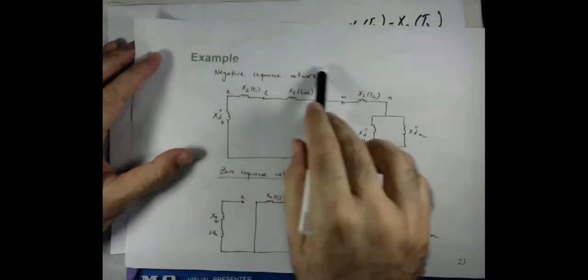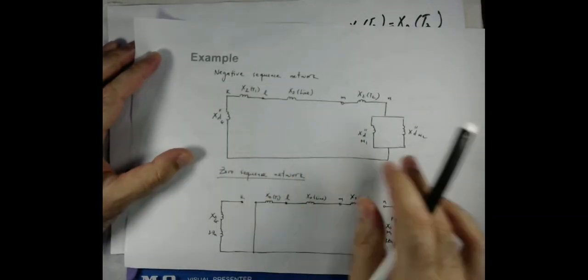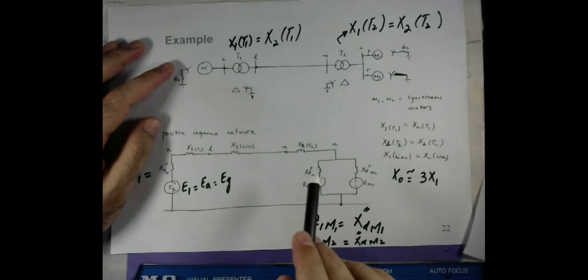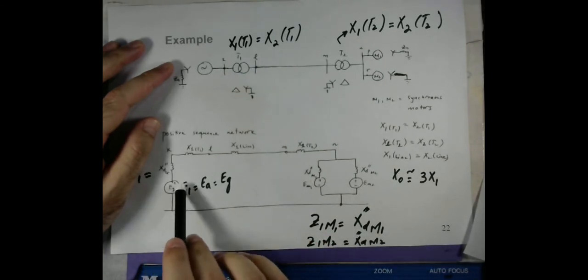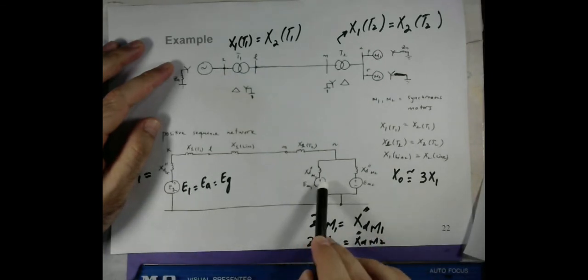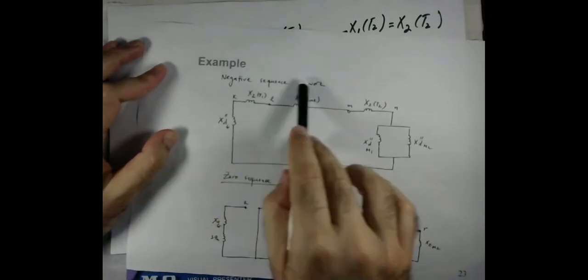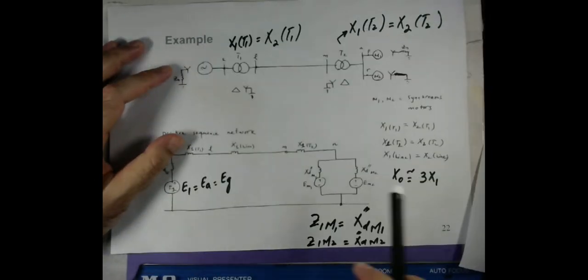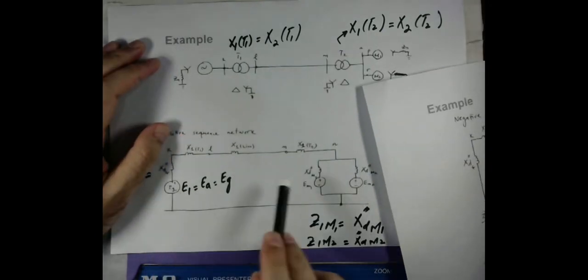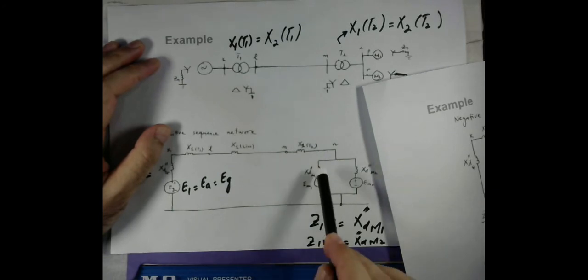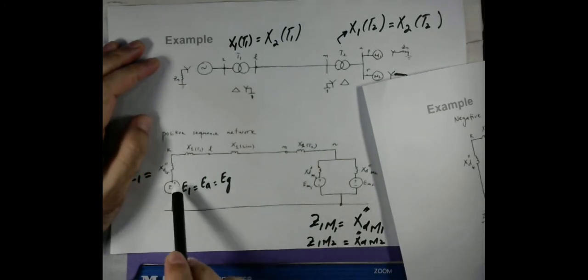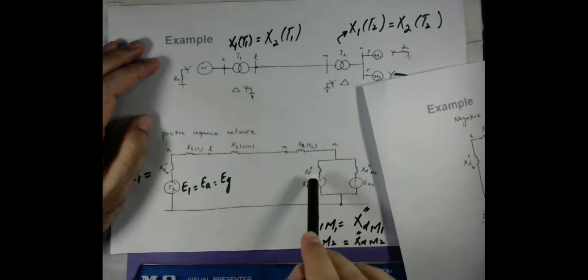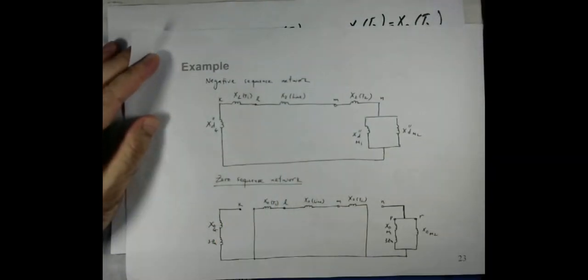So now this is the negative sequence network, the same as this one, but the only difference is that we make now the sources 0. So this will be the case now. So this is simple. We have discussed already this in detail. So by analogy, putting the sources equal to 0 and still considering the negative sequence reactances of the synchronous machine as equal to the subtransient inductive reactances, we get this particular network.